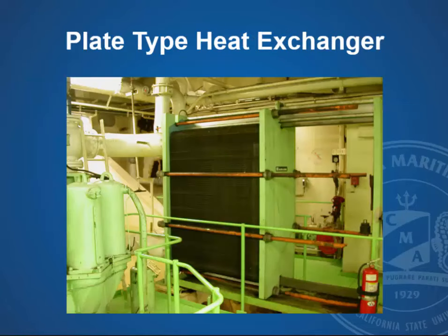Quite a majority of the heat exchangers on modern vessels tend to be plate type heat exchangers. You can also, by the way, have tube and shell. But I'm going to talk about the plate type exchangers for a little bit here. And these are sized appropriate for this freshwater to saltwater cooler. You also have seen them on the Bear. They're pretty popular because they're easy to disassemble and clean.